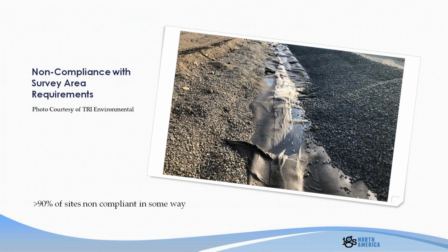Most of the sites that I survey are not completely compliant with the goal or the ideal of this standard. And this is part of our everyday life. I live on the East Coast. It's very wet here. This photo that you see is an isolation trench at a tie-in. This is what our isolation trenches look like. This is just a part of life. It rains the day before the survey, which is great because we know our landfill is leaking, but our isolation trench is a little bit compromised. This is fine as long as we document it.